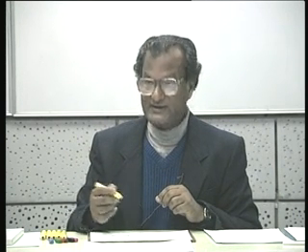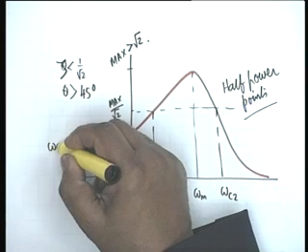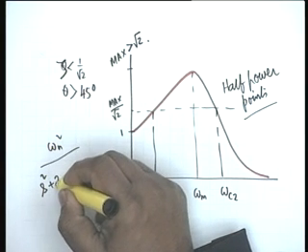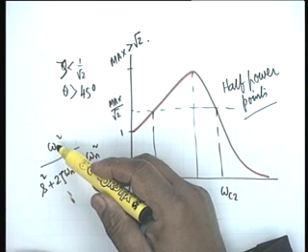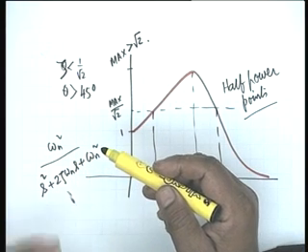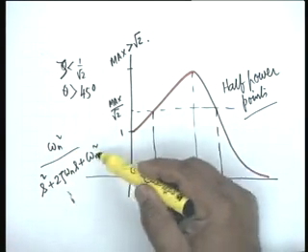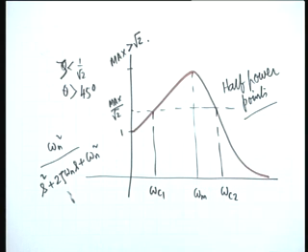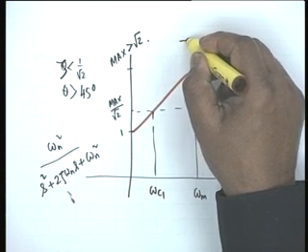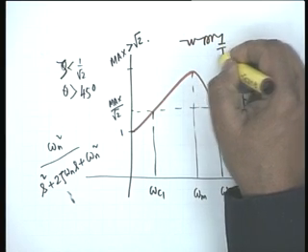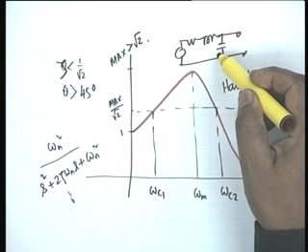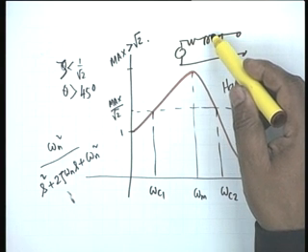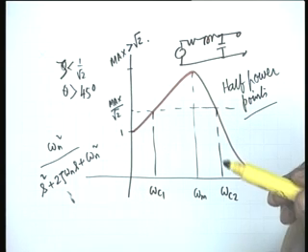Excuse me, sir. Yes. So this graph starts at 1. It always starts at 1 because the transfer function is omega n squared divided by s squared plus twice zeta omega n s plus omega n squared. Therefore, at s equal to 0, that is DC, the value is 1, omega n squared by omega n squared. It should also be obvious from the circuit. If you draw the circuit, we have a resistance, an inductance and a capacitance. This is the input, this is the output. If it is DC, the capacitor acts as open, the inductor acts as short, and therefore all the voltage appears here. So it always starts at 1.